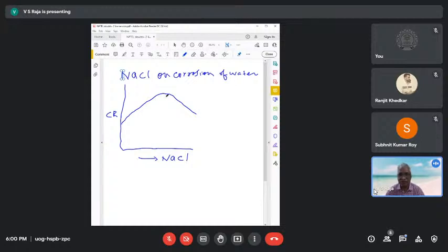And this is related to the fact that the cathodic reaction, or the reduction reaction here, is nothing but oxygen plus 4 electrons plus water gives you 4 hydroxide. Of course, the metal dissolution reaction is simple. So this is the cathodic reaction, right? But then this reaction is oxygen there.